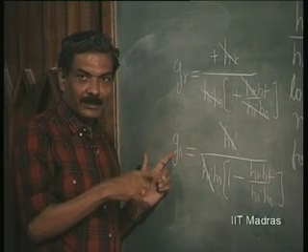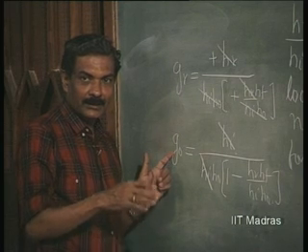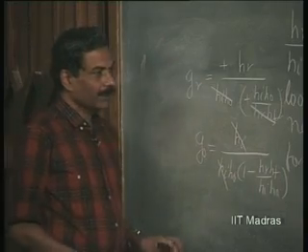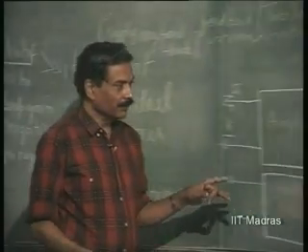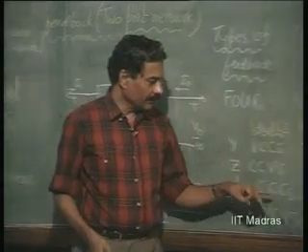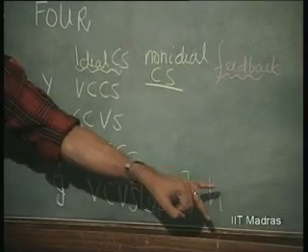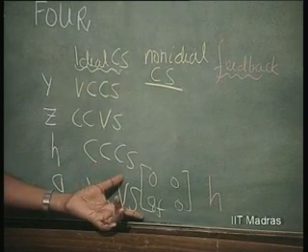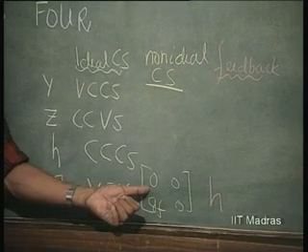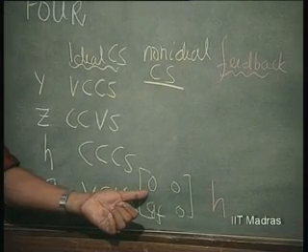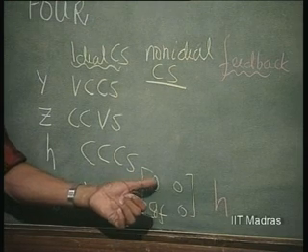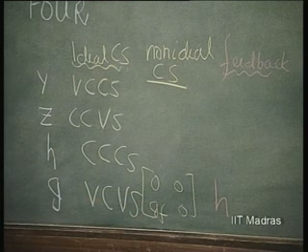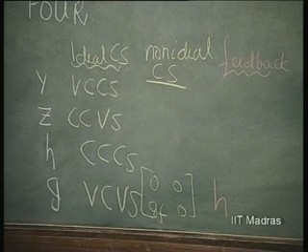So, all the parameters go towards 0 except the forward transfer parameter. We have now seen that all parameters go towards 0 by negative feedback of the proper kind, H feedback, in order that it becomes an ideal voltage controlled voltage source. So, we started with a voltage controlled voltage source which had non-ideal factors. These were non-zero, this was high, and we wanted to make it a good voltage controlled voltage source. Then we gave H feedback.